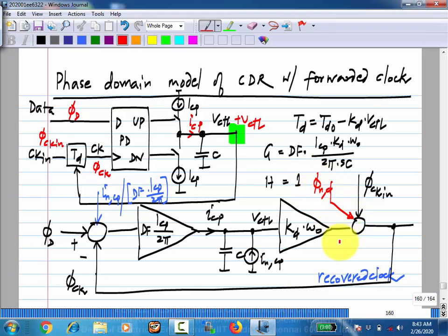That is the phase noise of the delay line. So this means that even if the input data and clock are clean, the output will not be clean. This is known as jitter generation. This is internally generated jitter. It is like the circuit noise: if the input is 0, the output will not be 0 because of noise. That's what you will get here.